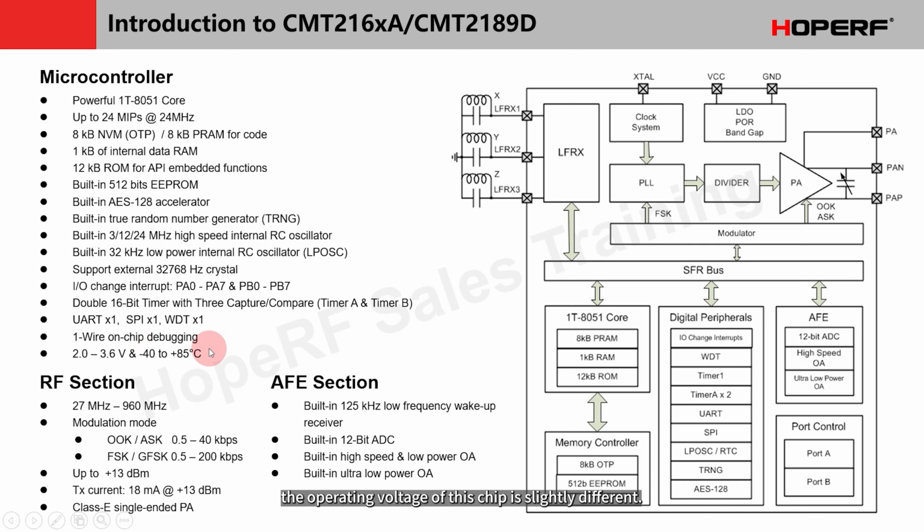Attention please. The operating voltage of this chip is slightly different. The minimum operating voltage of the chip is 2V. The range is 2V to 3.6V. The temperature range is -40 degrees Celsius to +85 degrees Celsius.